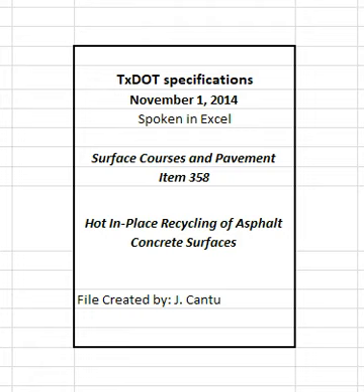2. Materials. 2.1 Recycling agent. Furnish a recycling agent in accordance with Section 358.4.2, Mixture Design, and meeting the requirements of Section 300.2.6, Recycling Agent. Other recycling agents may be allowed when approved or required when directed or shown on the plans.